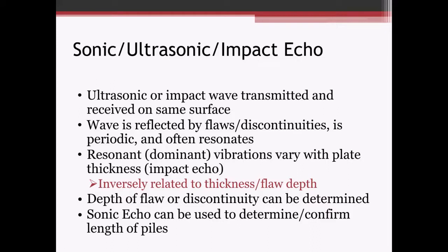The depth of the flaw can be determined, and sonic echo can be used to determine or confirm the length of piles. Also, if you have a 20-foot pile, you can estimate what the wave speed is in concrete.